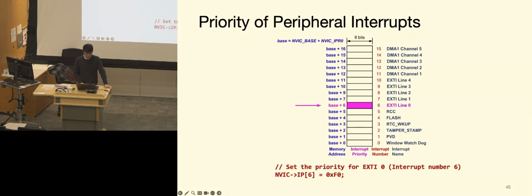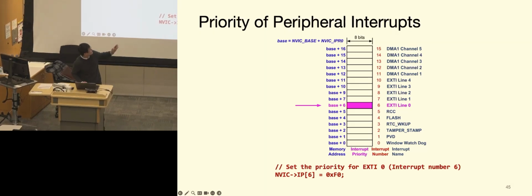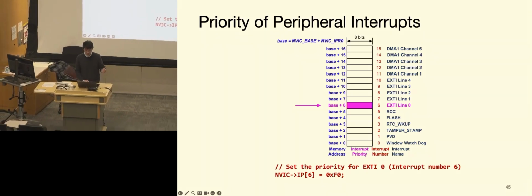Okay, so this is what the interrupt priority register in ARM Cortex-M essentially looks like, and they are implemented per interrupt. So each interrupt has its own interrupt priority register, or IPR, inside of the NVIC. Each of them has one, and they're all 8-bit. And then we'll be setting that based on the interrupt number, which is here. Each interrupt also has its own corresponding index.